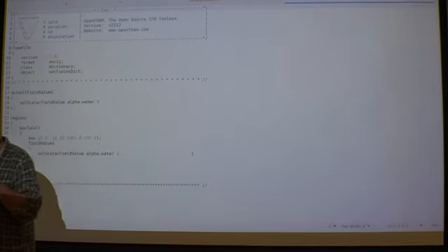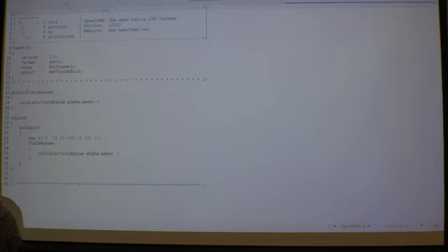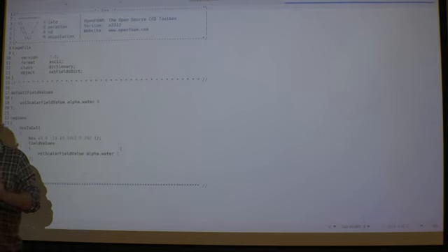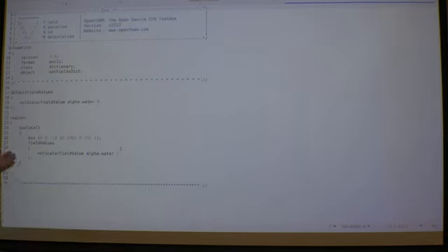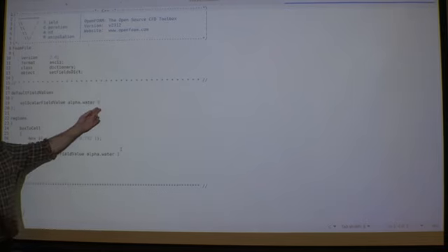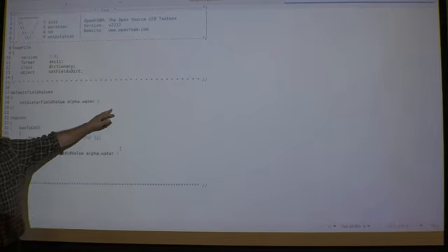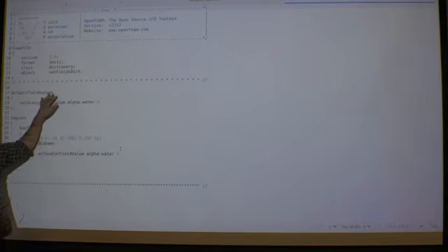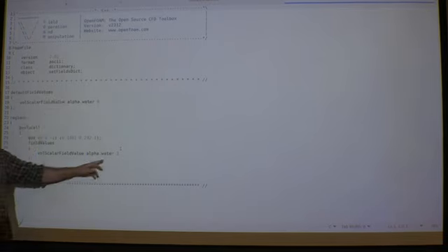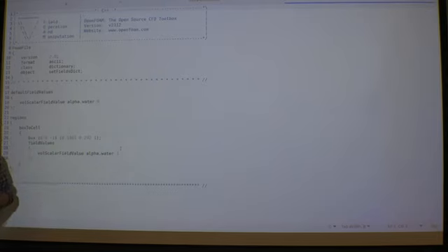So the job with setFields and setFieldsDict is to set up an initial distribution, and here for this alpha.water. You can use the same file actually if you want to set, say, initial velocities in different regions in your computational domain. So there you could have set velocity 0, then you need a parenthesis and 3 numbers, of course, it's a vector. 0 by default, but then you could say the velocity is 1 inside a box or inside an area. And you could have several areas actually. So you can do a lot with setFields.